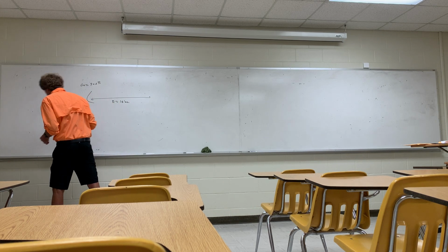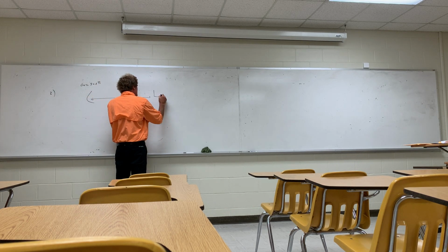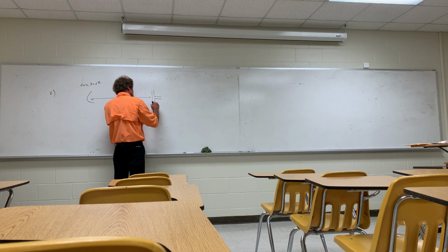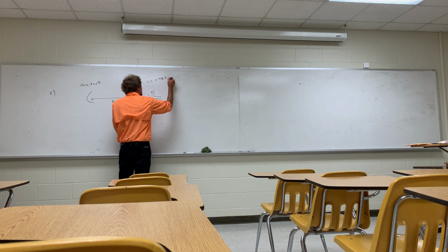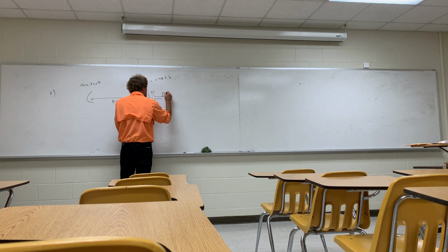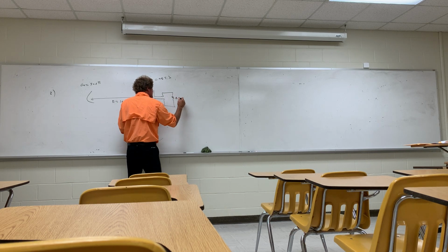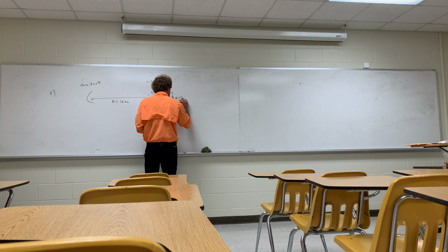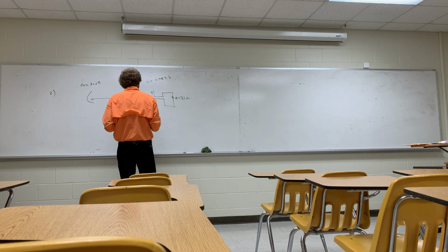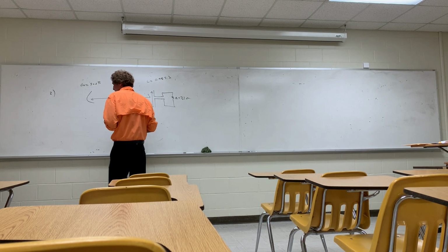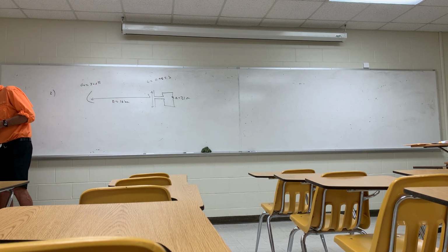And then you have a dipole with a length L of 0.485 lambda, and it's connected to R equals 72 ohm load. And from this one, I asked for first the power density incident on the